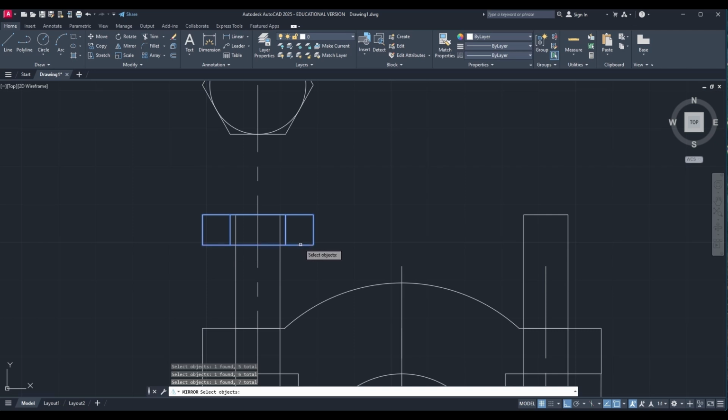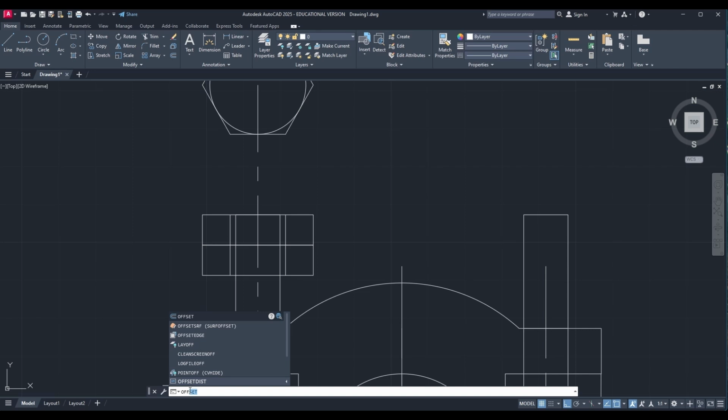After my selection is complete, I'm hitting enter and mirroring about this, like this. Okay, erase all subject now. So one is 8 and one is 12, so I need to use the offset option. Offset 4 mm downwards, then okay, 4 mm, then I select this and down.